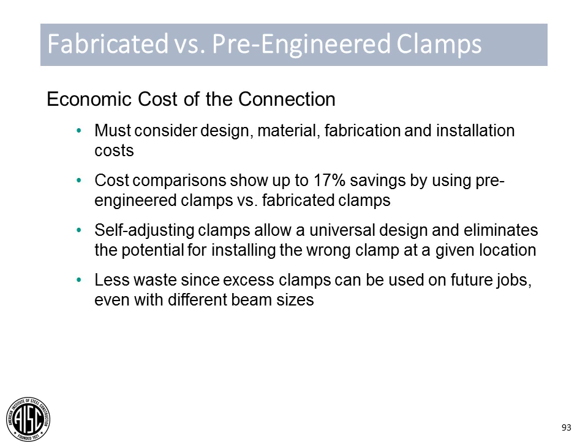And then you look at the economic cost of the connection. This considers design, material, fabrication, and installation. And it has been seen that up to 17% savings can be achieved with the use of pre-engineered clamps versus fabricated clamps.